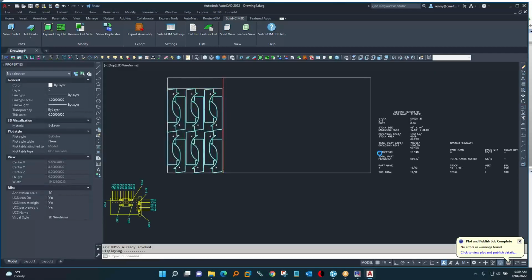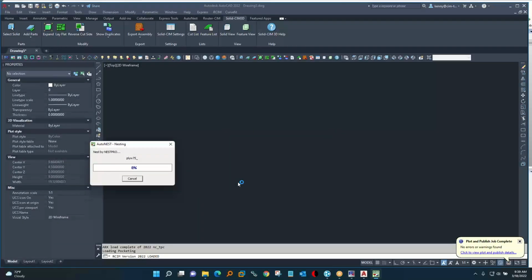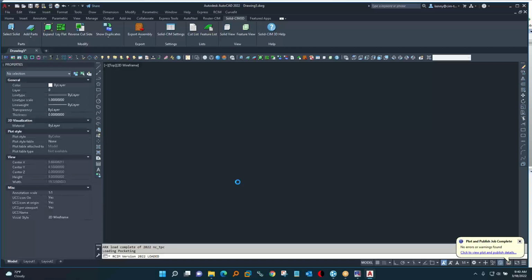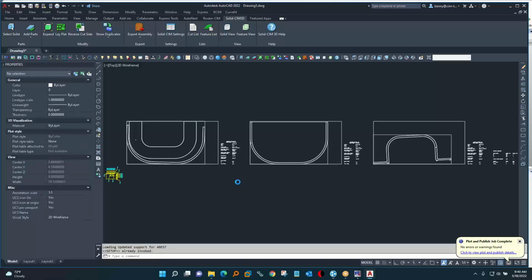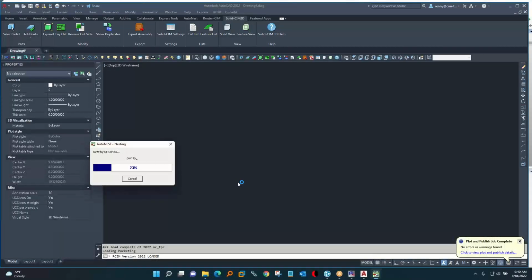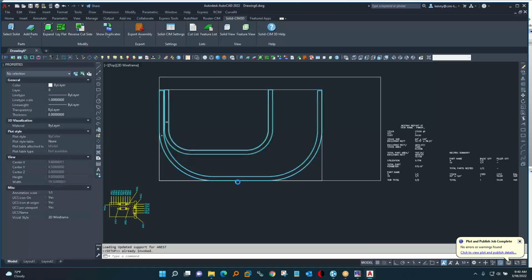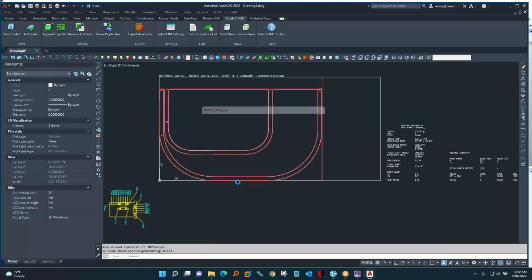And it makes a label for the scraps as well. So you can see the cutoff there. You can save that piece of material if you choose to. Fully integrated rolling scrap manager is what we call that. So each of these parts has a single program. I've got a nested program, and now the final sheets are completing, and we'll have all the labels and the reports built in.